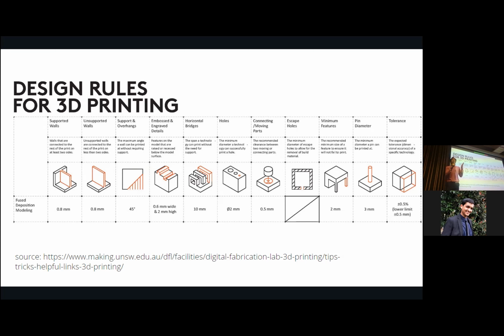So you know how I went through overhangs where basically you're just printing on the air, right? Bridges are like that, but kind of different. Imagine you have two vertical struts that you're printing up, like the supports of a bridge. Each one's about 1 centimeter tall, and then there's a gap between them, let's say 2 centimeters, and then you want to bridge filaments over it.